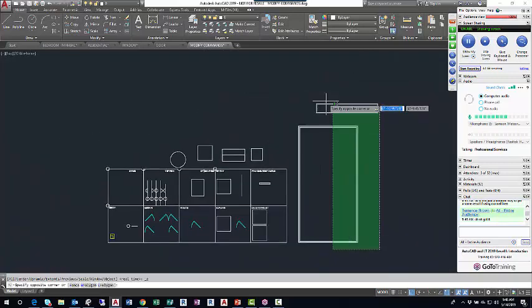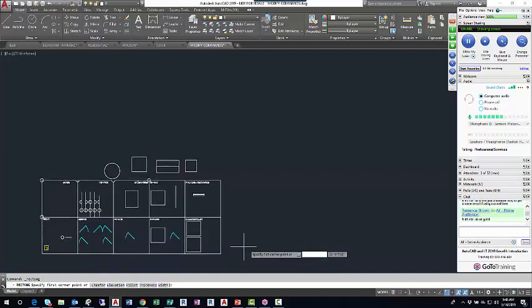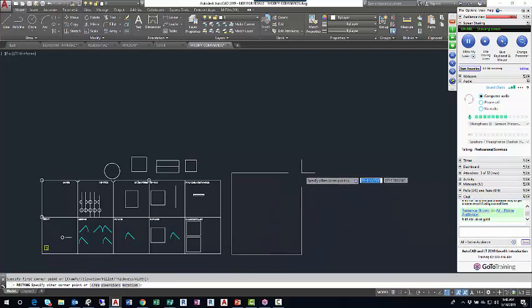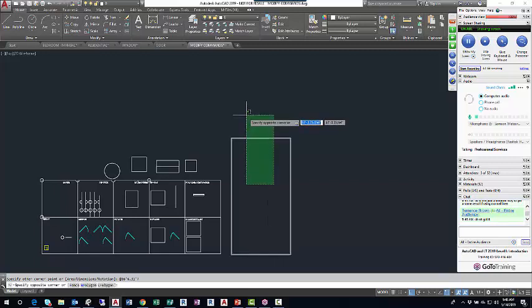All right, so one more time, let me delete this stuff and I'll recreate it just as a refresher. When we get into the floor plan exercise we're going to be working on, we'll start rectangle, left click. In our example, we'll start at the 0, 0 location, but in this example, I'll just left click to start it. I'll left click, move away from that corner, and now I'll type in my X, 16 feet 6, tab, 31 feet 7, enter.